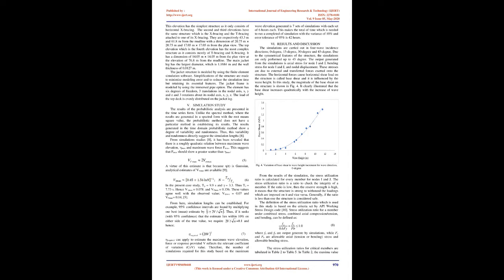4. Structural model. The structure used in this study is a medium water depth jacket structure which is installed in the South China Sea at the water depth of 73.3 m. It is a four-legged jacket that has 5 elevations that consist of horizontal, vertical, and inclined bracing as shown in Fig 3. Fig 3, jacket structure. The structure is made of steel tubular with the Young's modulus of 200 GN/m2 and a yield strength of 250 MPa. Each of the jacket legs is supported with a pile driven through the foundation and sealed with grout. The 4 legs are battered to achieve better stability against toppling.